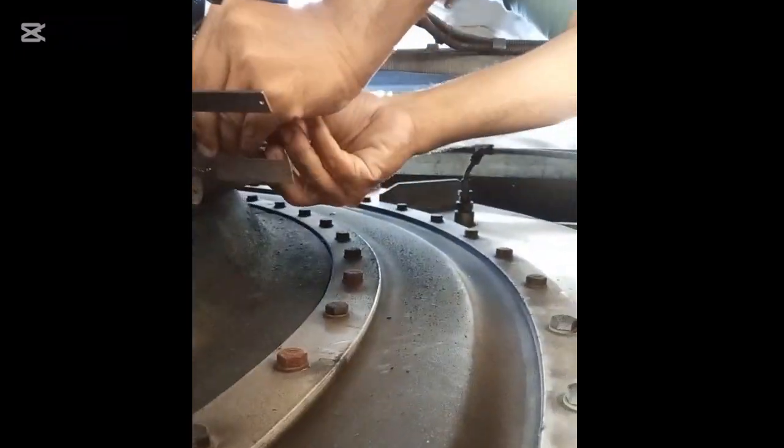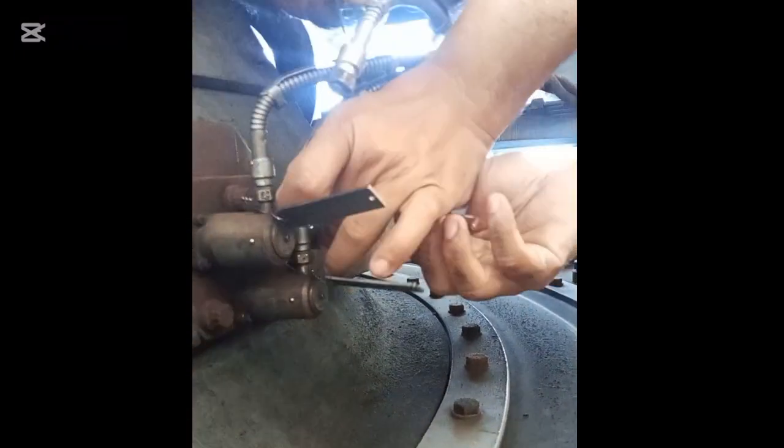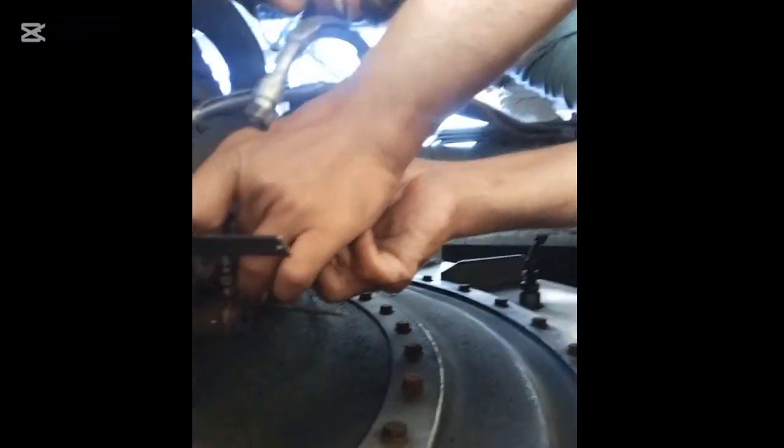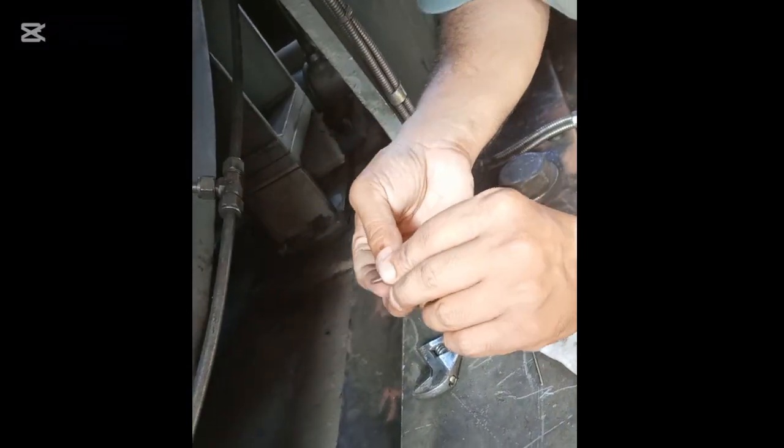We cleaned the dust from the sensor and then reconnected it. Also we measured its resistance, which is about 11 ohms, and then we connected the sensor, and after connecting the sensor we saw on our DCS server that the vibration is again fluctuating.